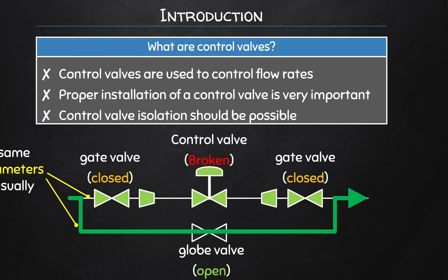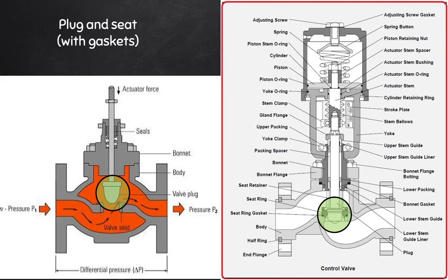Now, a typical control valve uses a plug that sits on a seat. There are some other variations depending on what is required by the process, but this is the go-to. Now, a gasket is usually present at the seat to ensure that when the plug is fully plunged towards the seat, a tight seal can form, stopping the flow completely. And obviously these gaskets and seals can be worn out over time, and so you would need to replace them. A typical control valve can be operated pneumatically.